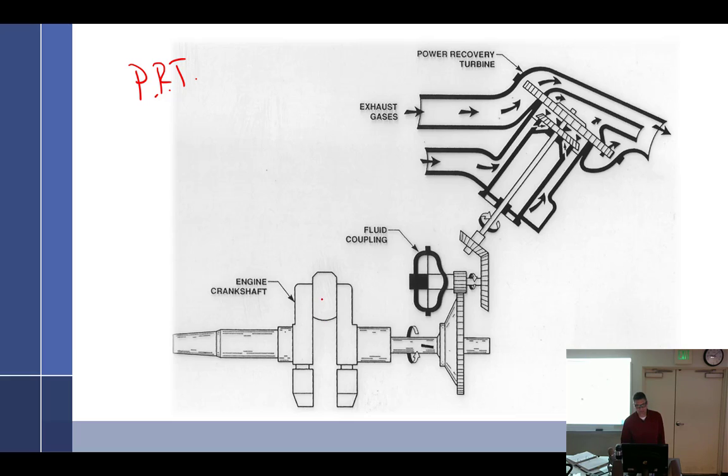We have a crankshaft, and of course it shows like it has one cylinder because it's a radial engine, which is only one throw. But you've got a direct drive shaft, but it does have a fluid coupling, so it kind of runs this way through the fluid coupling and then a smaller shaft back out. Follow that? So this shaft turns this gear, this gear turns the coupling. The coupling then turns another shaft that is inside of this, so it comes out here. Like a miniature reduction gear. I think it's fluid, like a clutch, like an automatic transmission. What do you call that? The torque converter. That's what I can picture it as.